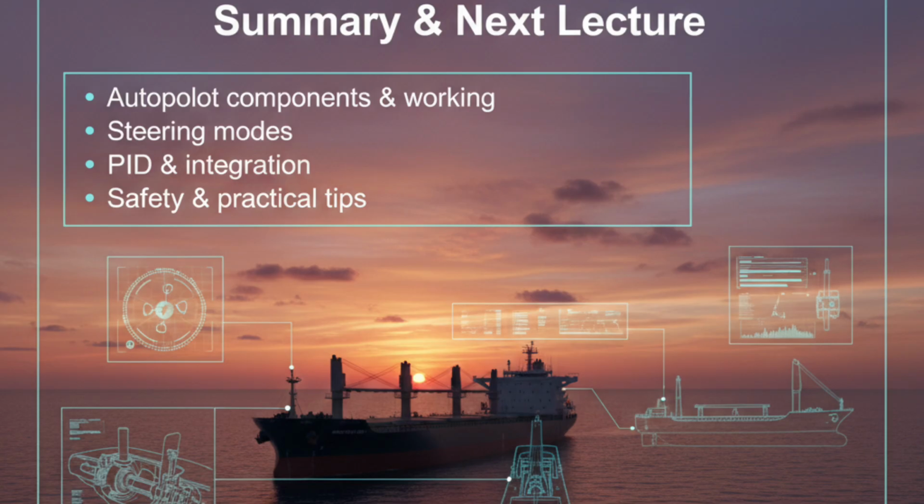We examined different steering modes, including hand steering, non-follow-up, follow-up, and auto mode, and understood when each mode should be used during ship operations. In addition, we covered the different types of autopilot systems, from basic heading control to advanced integrated bridge systems with GPS and route tracking.